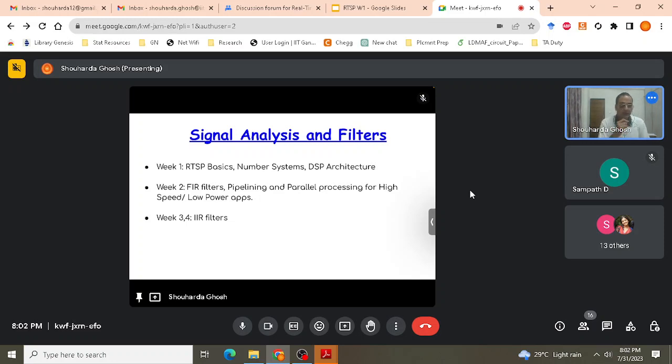Okay, basic FIR filters. What are the kinds of FIR filters? What are the different topologies? It's not that an FIR filter is just a few finite taps. Now these finite number of taps, H(z), you represent them as the summation of h(n) z to the power minus n, right? I hope everybody has studied FIR filters. Now a single FIR filter can be implemented in various ways.